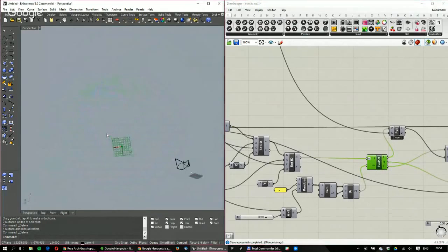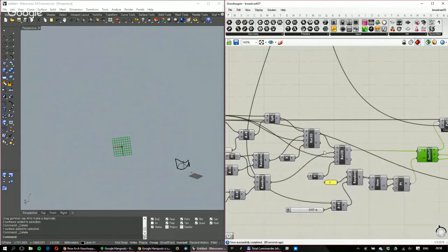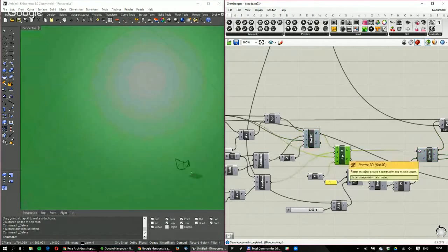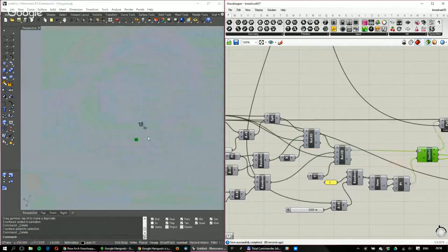This is the random point on the sphere. And also I care about the plane. The thing is that because of the way Rhino and Grasshopper works, this is never perfectly random. And therefore, I'm rotating the sphere as well to actually achieve a better randomness. So that's why I'm rotating twice, to actually rotate the sphere first and then select a random point.